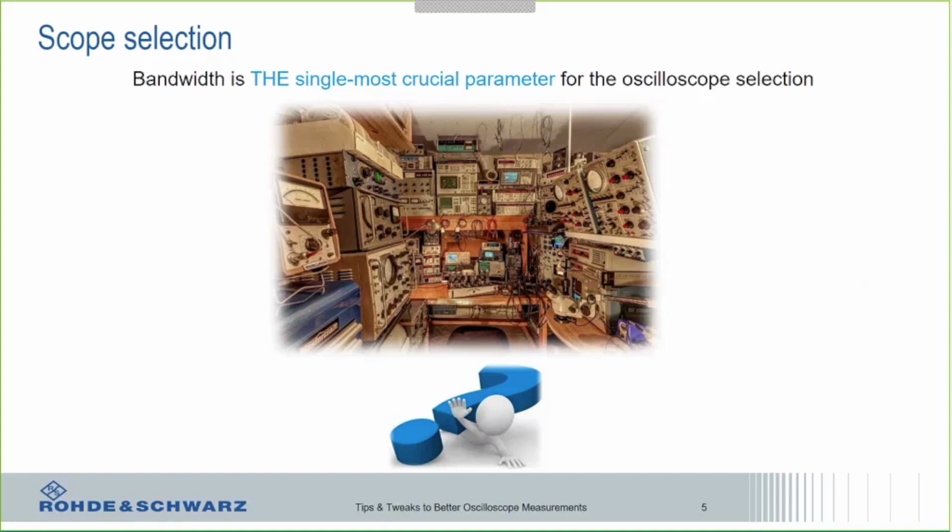And bandwidth is also a very big driver of the cost of the oscilloscope. Oftentimes you might be trying to decide how much bandwidth you can afford for the budget that you have. With that, you want to make sure that you're buying enough bandwidth to get the most accurate measurements, and at the same time, that you're not spending extra money that you may not have needed to.